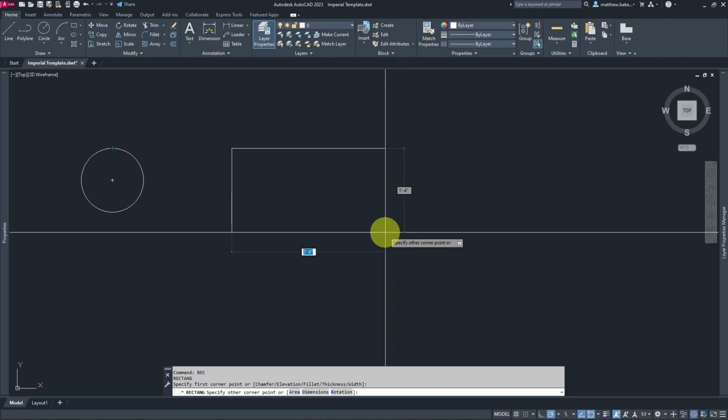And then we are going to go back to our rectangle, look at the bottom in the command line and see D for dimensions. So we want to input by dimension. So D, enter. And then we know the length from the drawing is 18 inches by 12 inches.